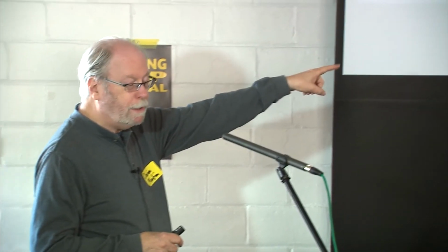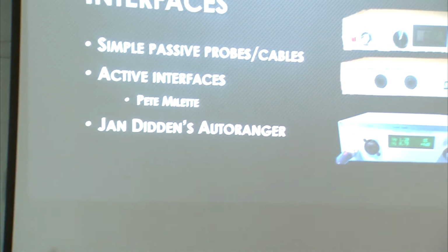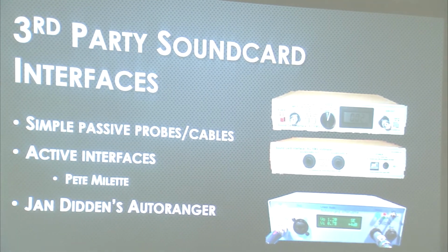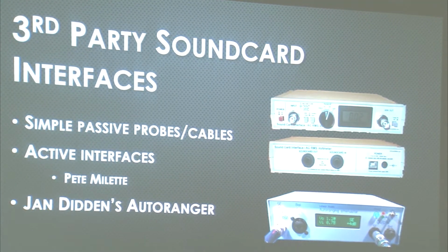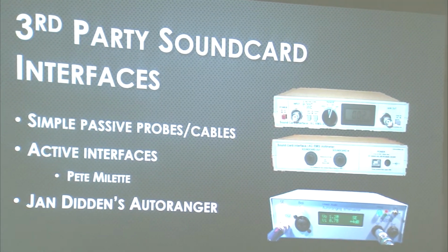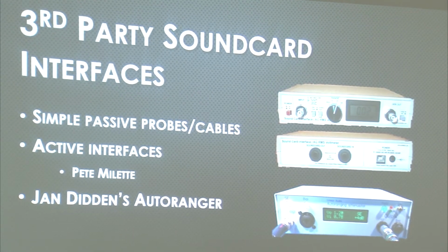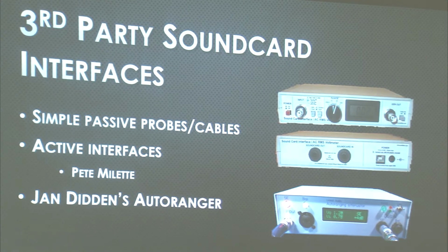Both of those have metering that tells you what's coming in. They have differential inputs, and that allows you to measure the signal coming out of your amplifier without ground loops. A good differential input will get rid of the problem that, if you don't have it, all of the energy from the power supply or from the current going out the output gets pumped over the input. You get ground loops and other confusers that really degrade the quality of the measurement. You want that differential input.